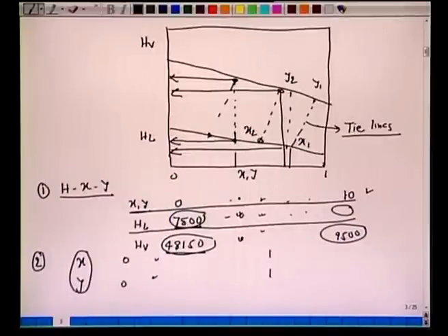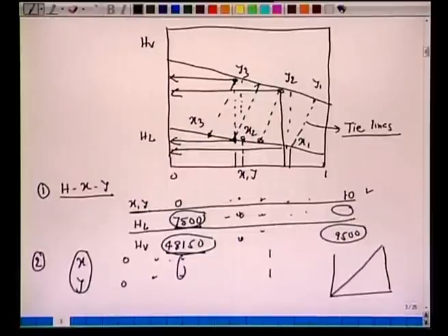Equilibrium for any composition of liquid, this x3, has to be obtained from here. So if I choose any point here and we ask the question, for a given x2 or some mole fraction here, what is the vapor? I will go to this table, maybe do some interpolations to obtain this y, but the enthalpy won't be the same enthalpy as this. We'll have to look for the enthalpy for the liquid here and the vapor here to obtain this on the tie line. Okay.